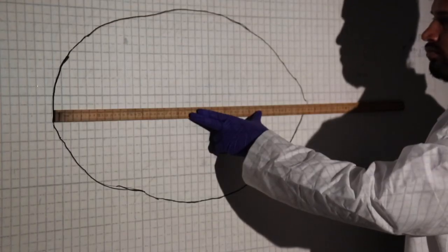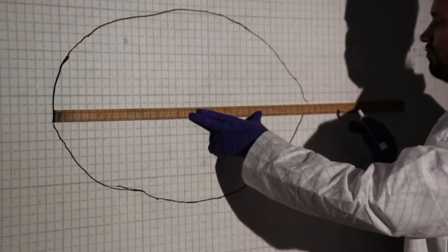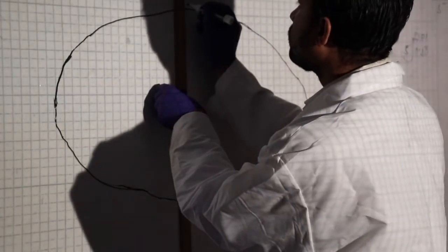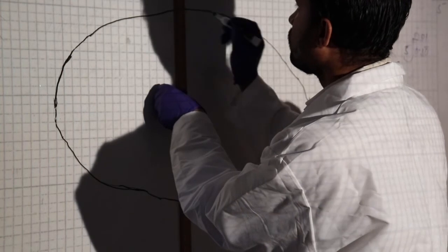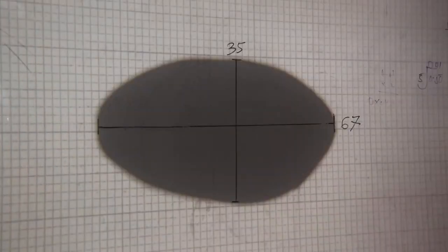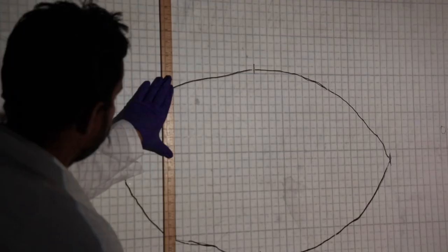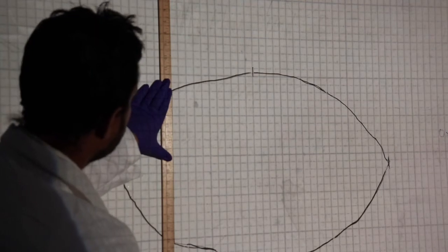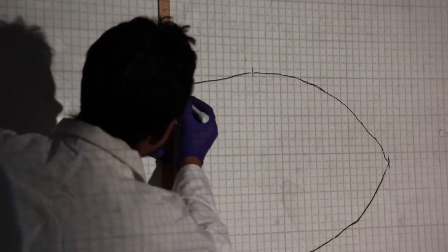Measure the projection of the major diameter for calculating the scale factor, and then measure the projection of the minor diameter to calculate the scale factor again. This scale factor should be the same or very close to the scale factor obtained from the major diameter projection. After that, divide the project area into as many of the largest possible rectangles as you can.